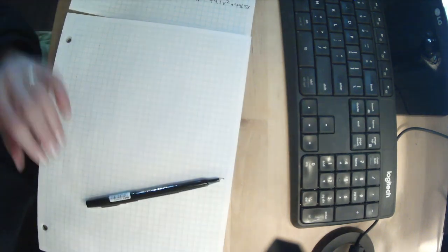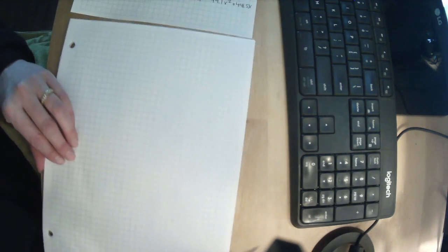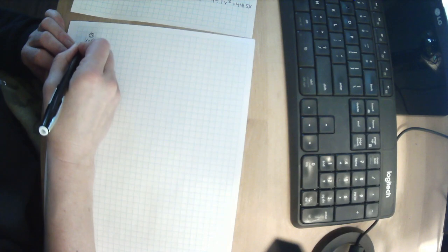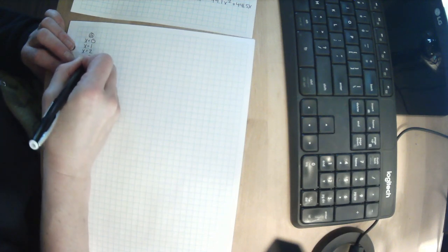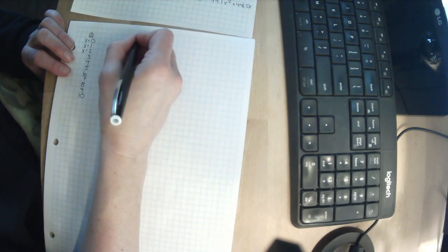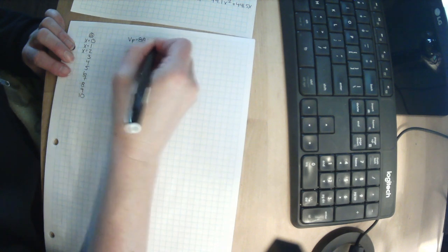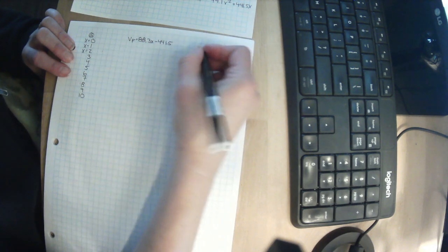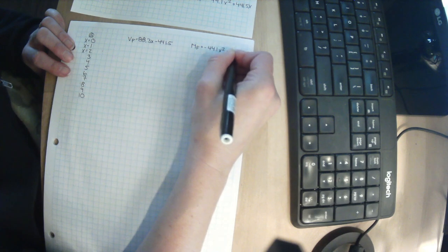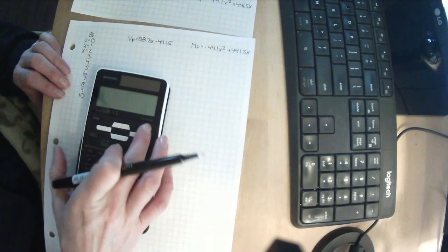Let's make ourselves a little chart and pick a few points along this beam. I usually find it handy at this point to make a little chart. All right, so at x equals 0, x equals 1, x equals 2, 3, 4, 5, 6, 7, 8, 9, 10. We know that VF equaled 88.3x minus 441.5, and MF equaled minus 44.1x squared plus 441.5x. Let's figure out what VF and MF are at all of these points.